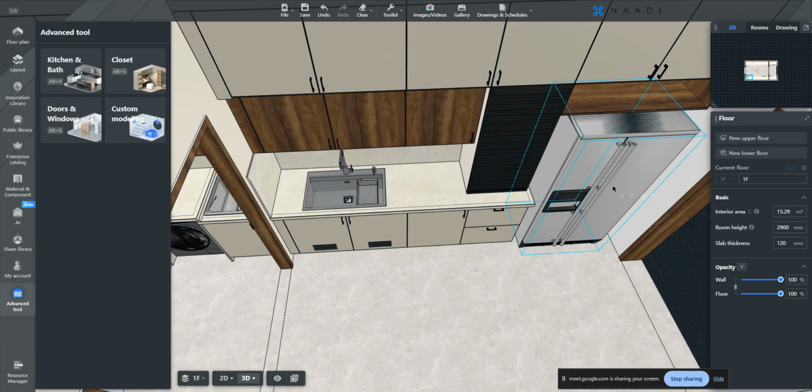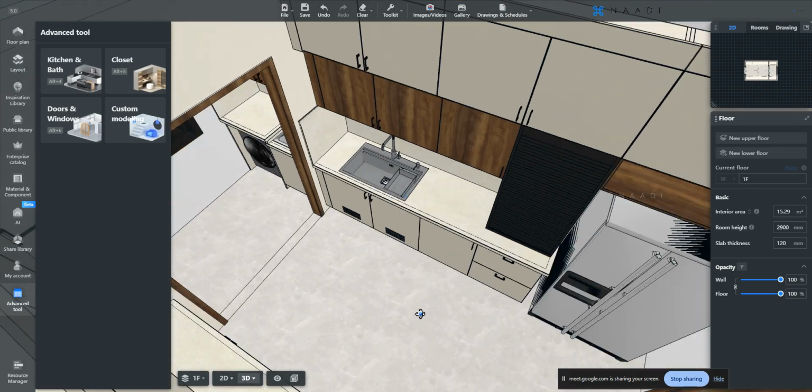Okay, and most important thing, please make sure that your cabinet placement is proper. Make sure that the depths are properly aligned for your base unit, wall unit, and loft unit, because this is where I commonly noticed your misalignment, your dimensional misalignment in the 2D. They mention that there is a misalignment, but that is technically the model misalignment here, which is getting reflected in 2D. So make sure that this is all done.